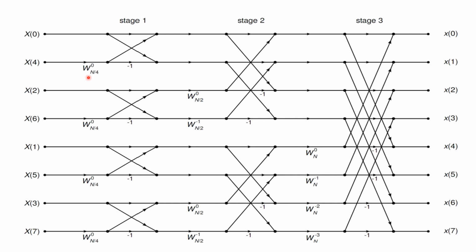So since our n is equal to 2, if you find the twiddle factor or the phase factor W 8 by 4 power 0, which is W 2 power 0, 8 by 4 will fetch us 2. So W 2 power 0 is the twiddle factor used for our first stage of computation.